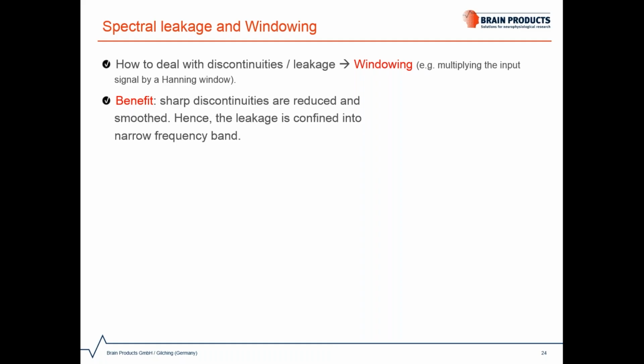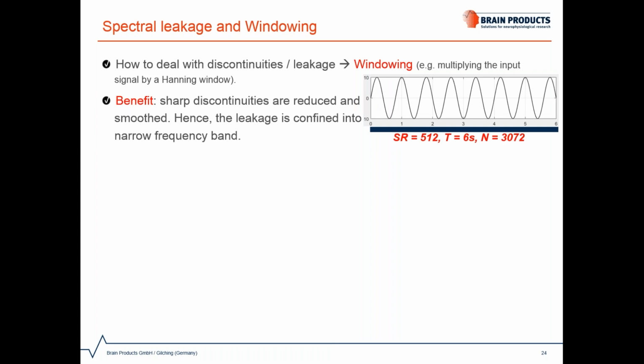So, is it really possible to find the actual frequency even when spectral leakage occurs? Yes, you can achieve that by having a finer frequency resolution. To illustrate this with an example, let's use the same signal and this time apply FFT on the entire 6 seconds. The longer the signal duration, the finer the frequency resolution gets according to the formula. Care should be taken though while prolonging the duration of the signal of interest, because the longer the signal gets, the less stationary it becomes.